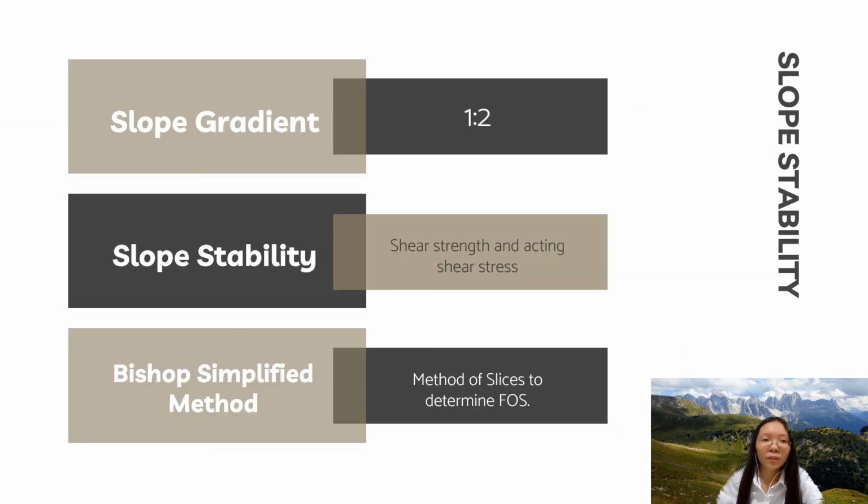The last part of the earthwork project is to check the slope stability. Slope stability is generally controlled by the nature, distribution, density, and strength of materials that form the slope. When we cut a slope, it will reduce the total stress in the slope and lead to the reduction of pore pressure and hence increase the slope stability in the short term. When the pore pressure rises to a new equilibrium value, the materials in the slope may become weak, leading to a reduction of the slope stability.